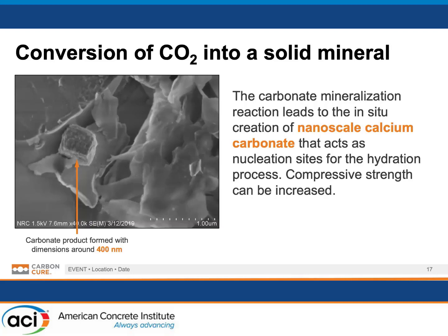And as I've shown you, we can see this in the macro property of compressive strength. So this is an example of an SEM picture of a CO2 injected system. I can't remember if it's cement or tricalcium silicate, but in either case, what we're seeing is an approximately cubic particle that is formed in the concrete or in the binder system. And this would have been hydration arrested within a minute, maybe 2 minutes of the injection of the CO2. So this is very early stage hydration.